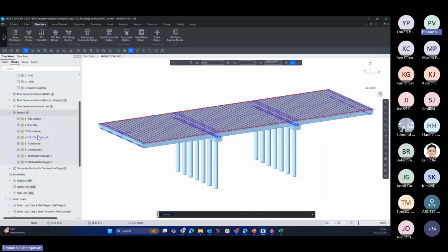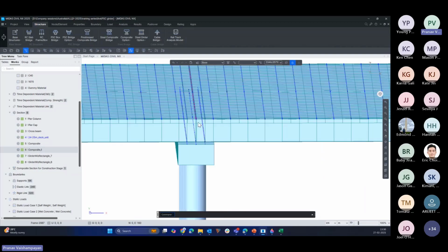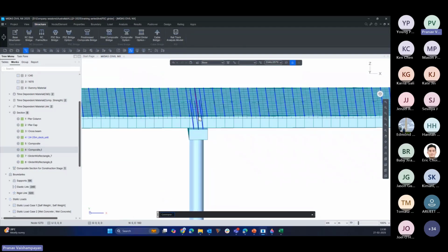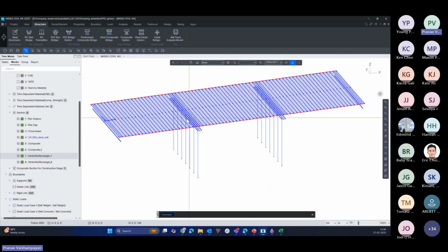Sections. So we had defined 5 sections. A 6th section for the continuous slab location is created, a very small, thin section. Then extreme end girders, just dummy 1 mm by 1 mm girders to provide enclosure closing to the grillage element, are created. And the transverse deck slab unit at 1 meter locations are created.